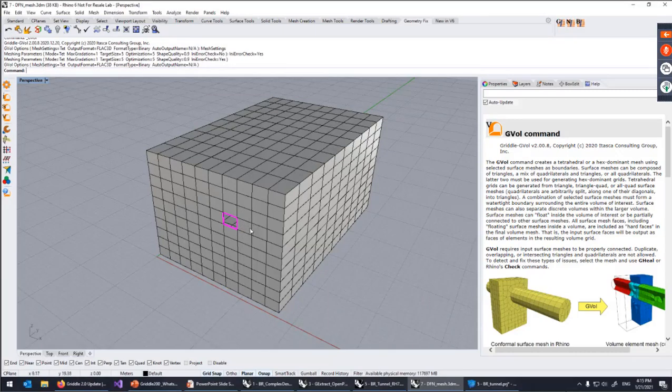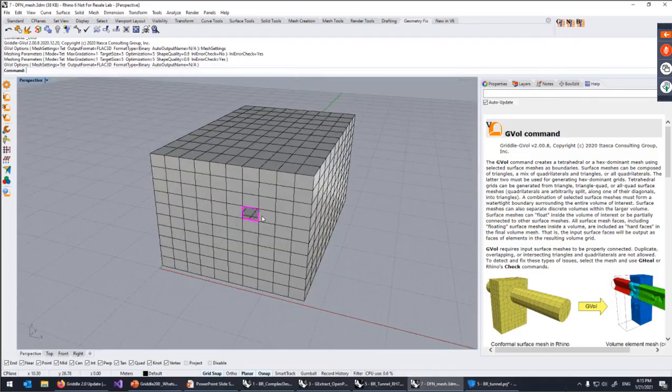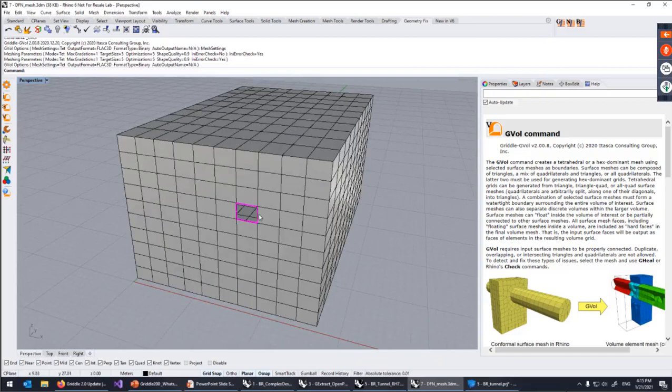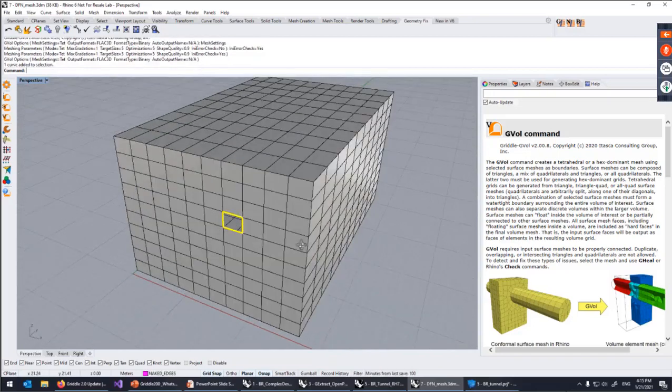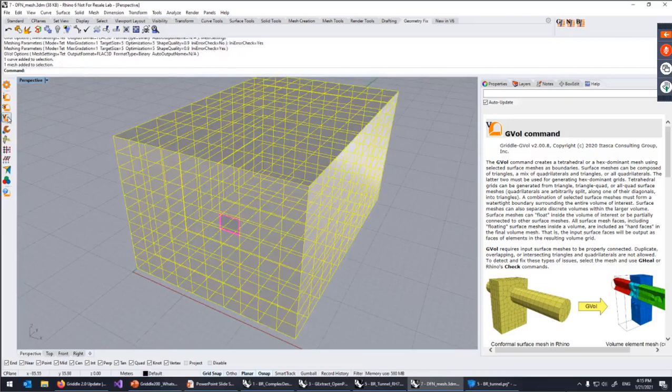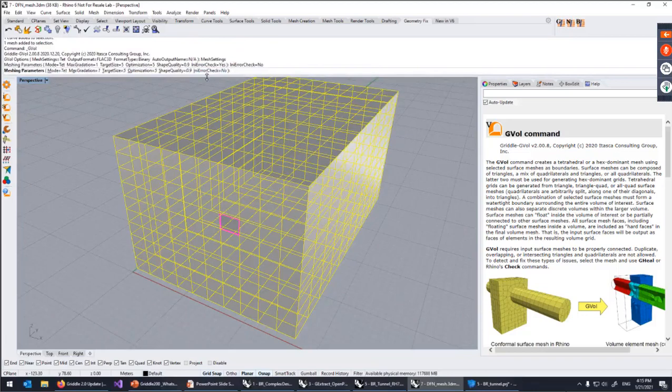However, it will show such a message, let's say, if there's an internal surface that kind of floats within this domain. Such a surface may contain naked edges, and this mesh will be shown as well. So you have to be kind of discreet about this message, and if you see it, maybe go back and analyze what's happening, if that's really a problem or that's by design. And you can turn off this message by going here into advanced settings and just say, I don't want to see this message anymore.